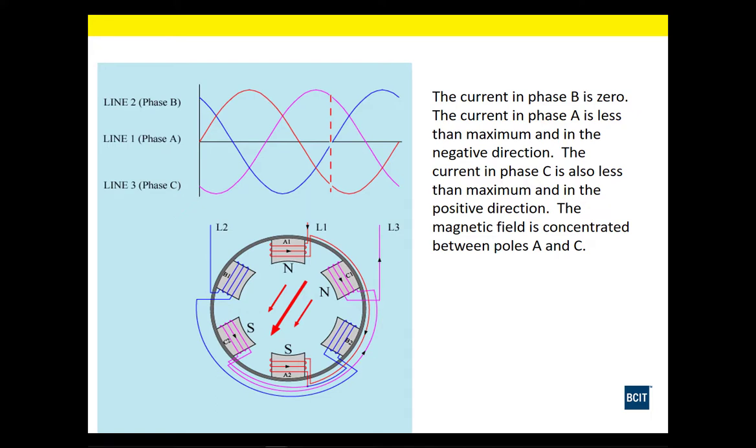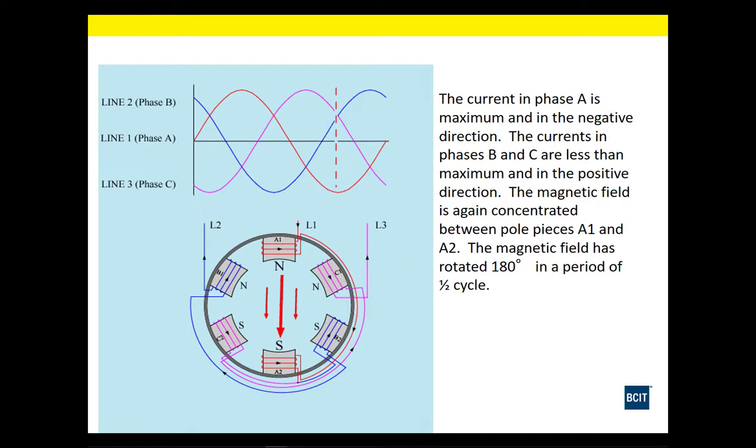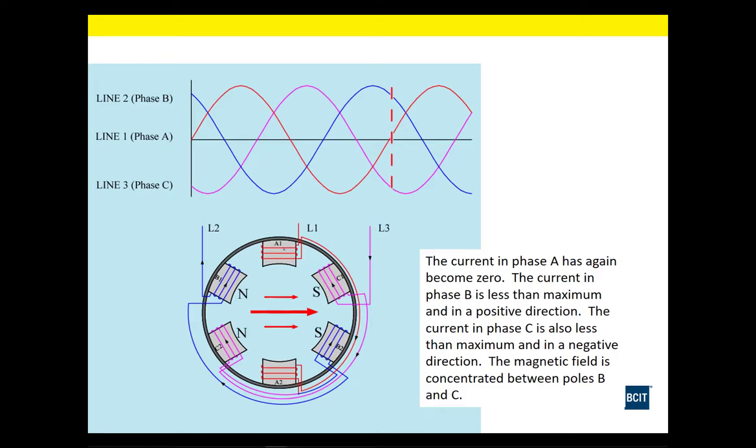Now B phase is de-energized with no current flow, so we have no north or south poles there. And then the next increment, we have A phase peaking in the negative half cycle, so its polarity, where it originally started the cycle with this south and this north, is now flipped because we're at the negative half cycle. And later, at the next one, where A is going to cross 0 again, we have equal and opposite currents at B and C phase.